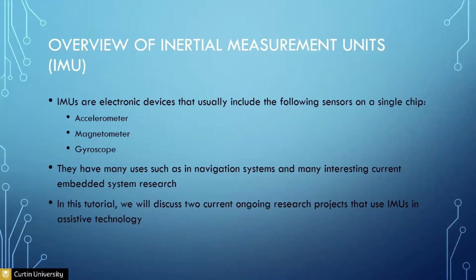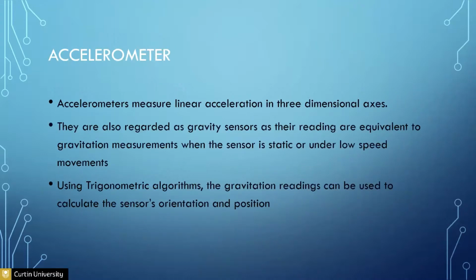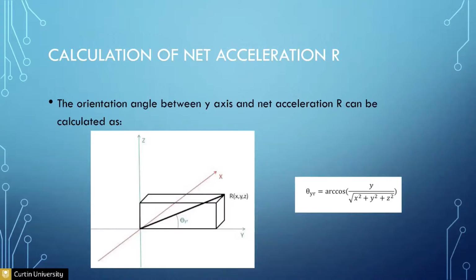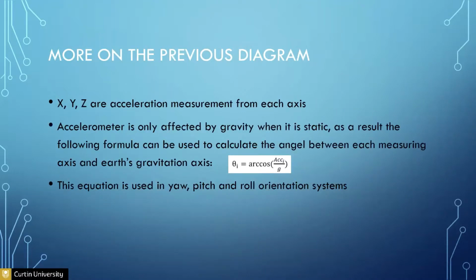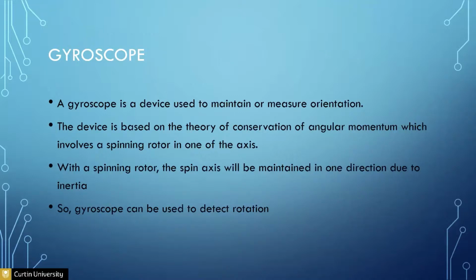tea in between. Now, another useful sensor, and one of Ian's favorite sensors, are IMUs. They're basically an accelerometer, magnetometer, and a gyroscope on a single IC, or sometimes divided into two separate ICs with the accelerometer and gyroscope on the same IC, and the magnetometer separately. With the accelerometer, we can convert the information to pitch and yaw, so we can capture movement because we are getting information from three different axes. And with the gyroscope, we can get rotation.